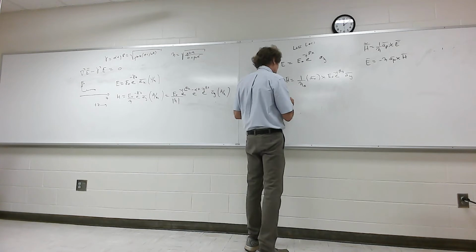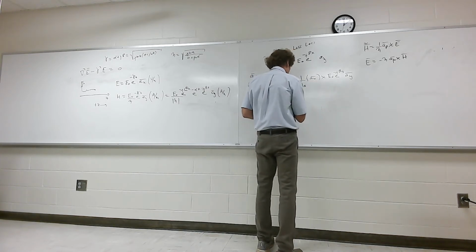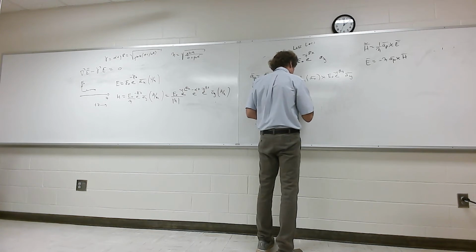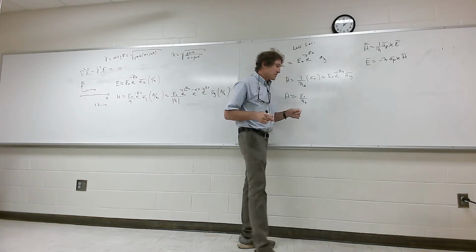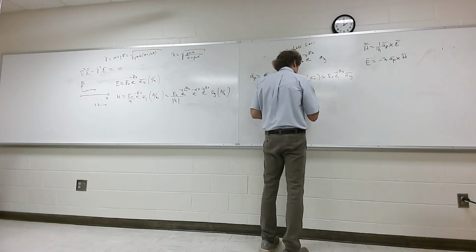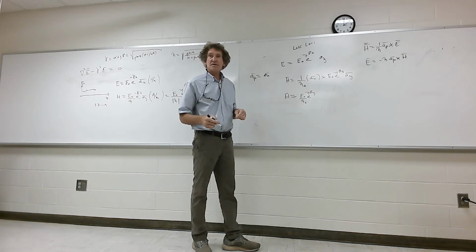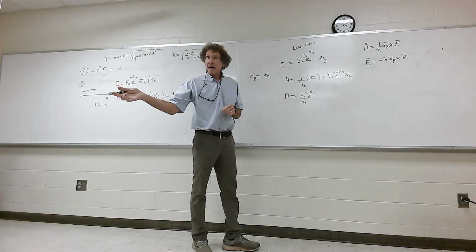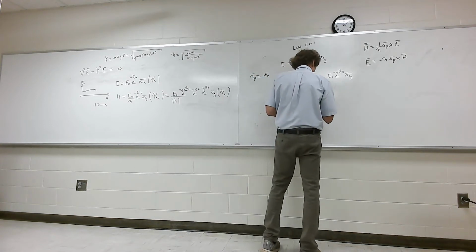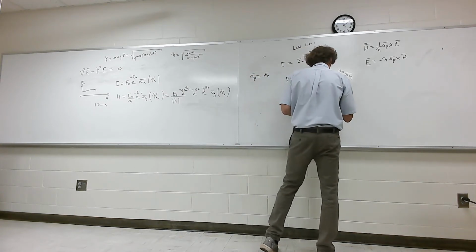So now, what is the H field for this one? Well, in magnitude, it will be just E naught over eta naught. Y'all agree with that? Now, this e to the minus j beta y is going to just stay there, it's going to do nothing. What happens when AX crossed AY? It is AZ. So that would be the H field, that would be in amps per meter.